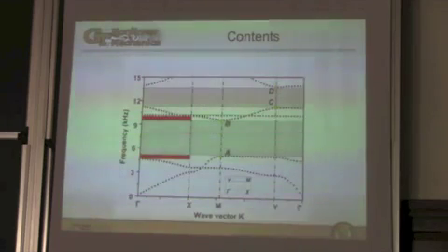But maybe more importantly, we can cut through the material and make a waveguide. And that's done, for example, or can be done in your cell phone. Your cell phone actually filters with a surface acoustic wave device. Many of them are now phononically enhanced, all right, to get rid of some frequencies that otherwise would pass through. So this bandgap's critically important. We can put a defect in, and then we can have a very high Q resonator in the structure. You can use RF applications where you're using piezoelectric materials and mixing this band gap to do filtering of electromagnetic waves. All right, so there seems to be a lot of promise with these metamaterials.